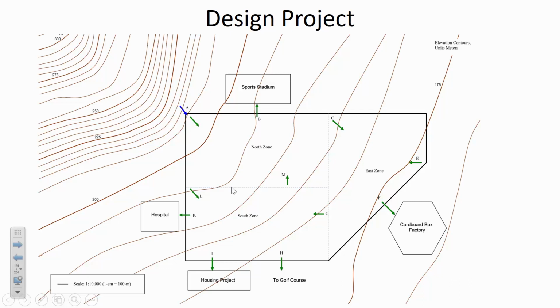You do that planning really to get an idea of what the scope of costs would be for a development. If this is some raw land that needs to be developed, you can assume that you've been hired by the land developer to identify what the pipe network should be to make sure that there's enough water at each of these locations. Of course there are going to be secondary pipes inside of the network, but probably whoever's putting in the neighborhood would be in charge of putting in those secondary water lines. You're just providing the main stem of the services.